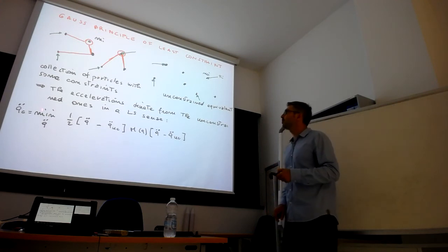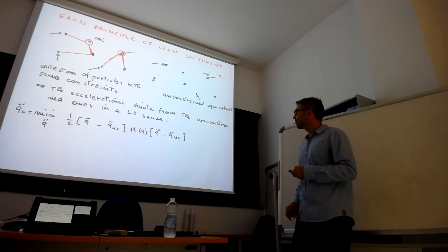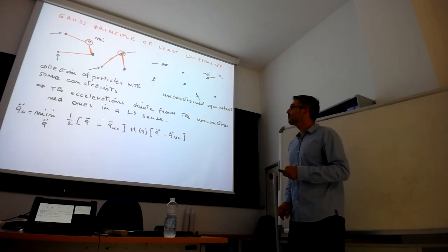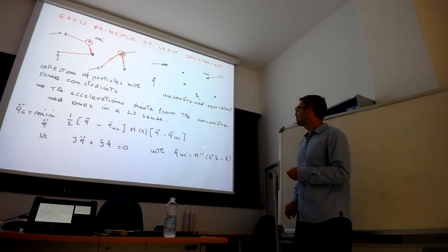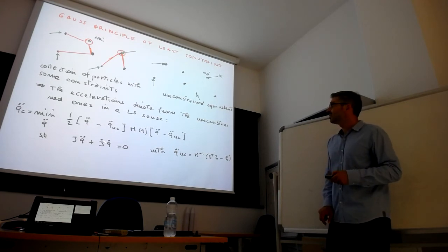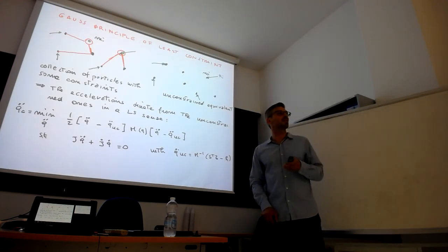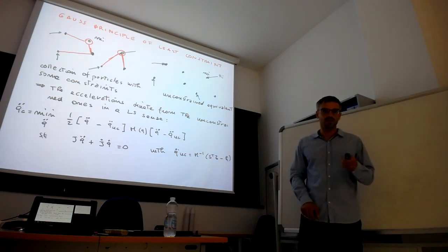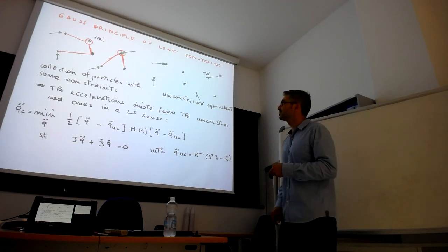So in essence, you solve a QP. The constrained accelerations are the ones obtained by solving a QP, where you try to minimize the quadratic norm, weighted with the inertia matrix, of the distance from the unconstrained acceleration, subject to the contact constraints. We compute the unconstrained acceleration in the case of our robot as the usual dynamic equation without any constraint. You plug this in, you solve the QP adding these contact constraints, and the q dot dot constrained that you obtain should be consistent with the q dot dot that we computed with the projected constraint inverse dynamics, constraint dynamics. It's done, and you can verify this is true in the lab.